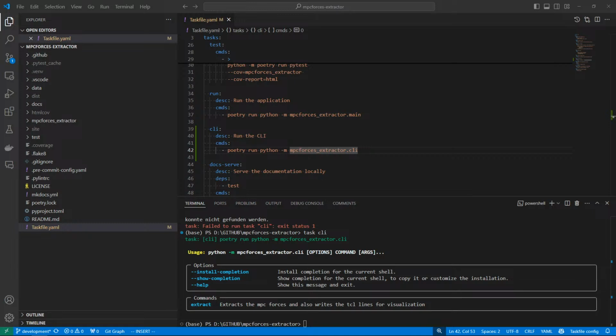For example, to get knowledge from data or something like predictive maintenance. That's something where you apply a little sensor on your product, and if it detects some, how would you call it, some behavior, some data which is not in the norm, not something your model trained on good running products would ever produce. Just think about when a wheel has something like a crack, the vibration will just be different, and so you can detect something like that and say to the user, well, hey, do you have a problem with your wheel?